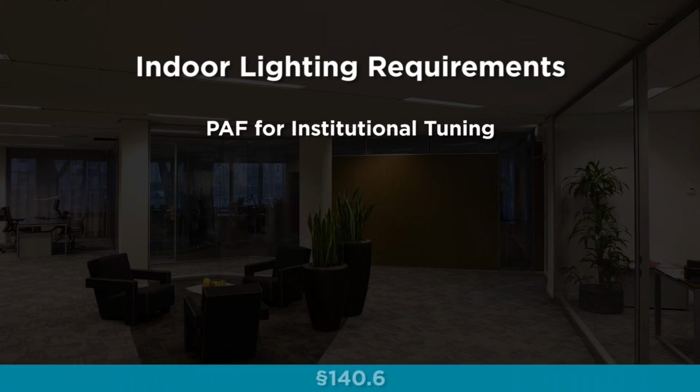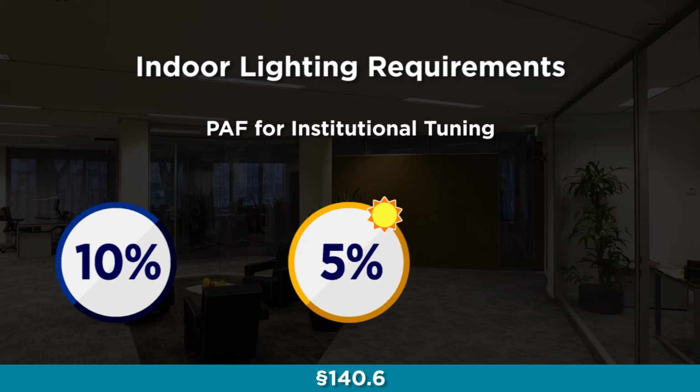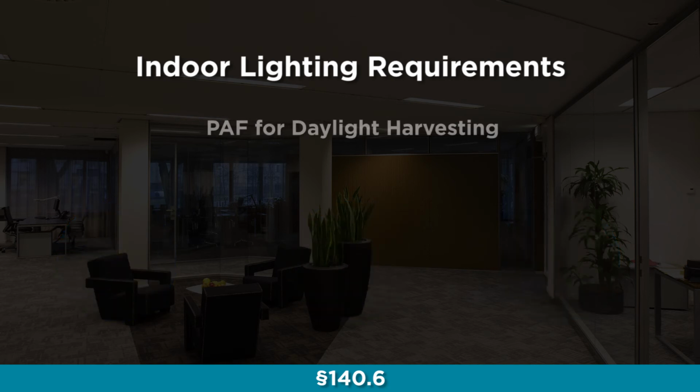Institutional tuning is a control strategy that sets the maximum output of a lighting system to less than full output, delivering the right amount of light while using less energy. Projects may gain a 10% lighting power allowance credit for implementing institutional tuning. In daylit areas, the credit is reduced to 5%. Acceptance tests for institutional tuning controls are documented on a new compliance form, NRCA-LTI-05-A.